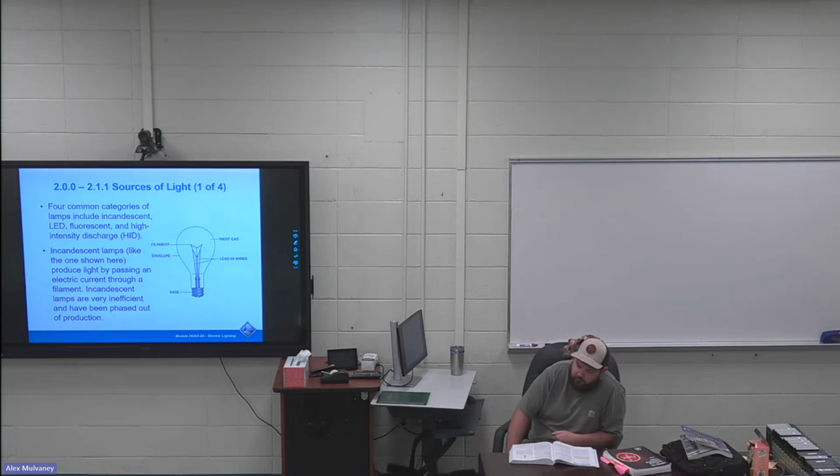And then I've got all 3 of the bullet points highlighted separately. First one, color temperatures of 3000 Kelvin and lower are described as warm in tone and slightly enhance your reds and yellows. So if you've installed any of these LED lights before, a lot of these pancake lights or pan lights, they have a little switch on the side that lets you switch what the temperature is on the light, so you can go from warm to cool.